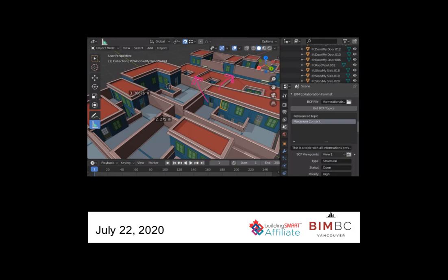This one's a bit interesting. The BlenderBIM add-on also supports BCF. And BCF stands for the BIM Collaboration Format, as you can see here. And so every time you do issue tracking, this is a standardized way to store information about the issue. Things like the status, the priority, the discipline, as well as certain viewpoints. And then if you scroll down here, which is not shown in the screenshot, it's got a whole bunch of other metadata and comments. So the ability for somebody to view your issues in one program versus another is made possible by things like BCF.